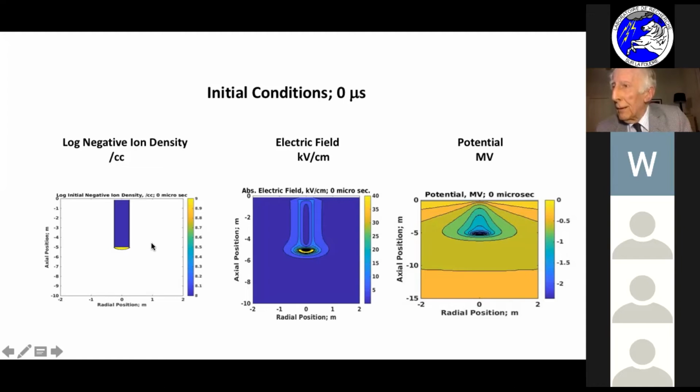Now, with that initial structure, which is arbitrary, and if you change that, you get all sorts of different answers, the calculated electric field at the tip here is of the order of 40 kV per centimetre. And for ionization, you only need 25 kV per centimetre. So this high electric field is going to start producing electrons and ions, and the field everywhere else is lower.